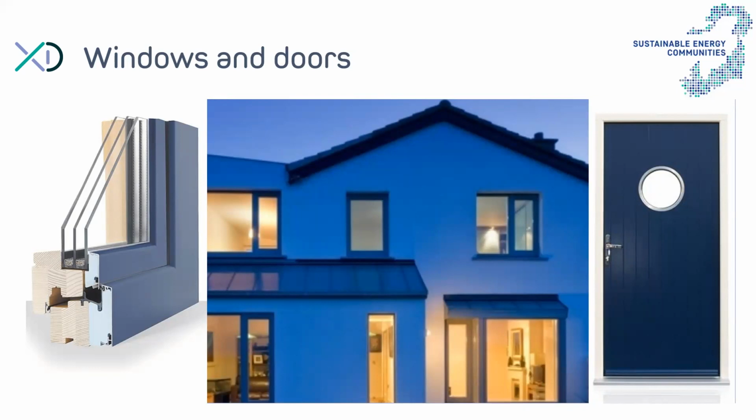And if you do that, we'd recommend good quality double glazing with an insulation gas between the two panes, and a reflective coating that will, let's say, trap the infrared radiation inside the home and reduce heat losses, making sure that they are airtight, that they close nicely and tightly, so that there are no drafts.